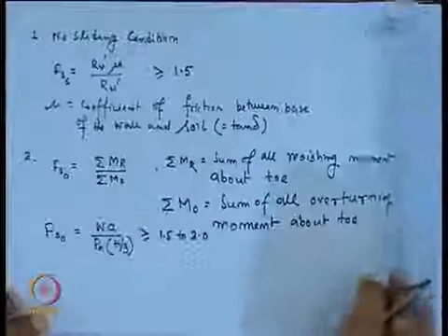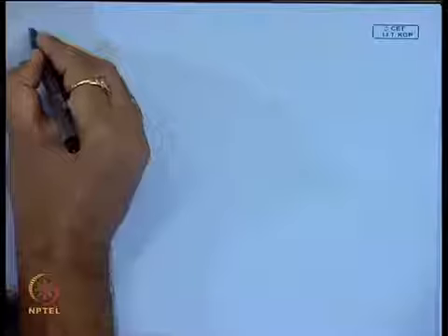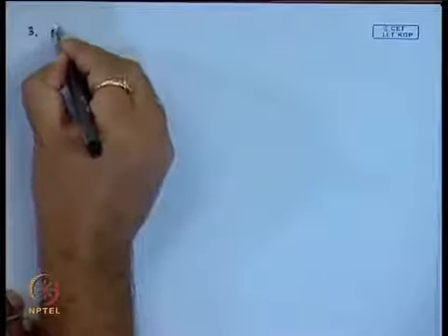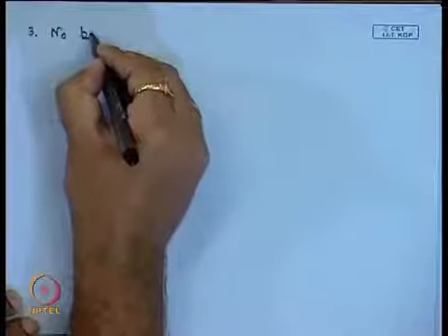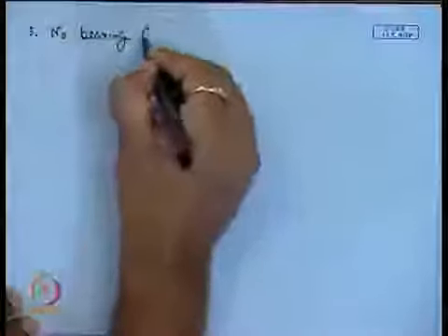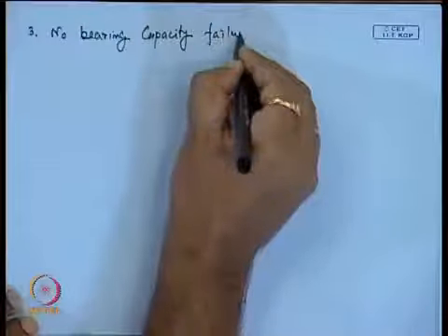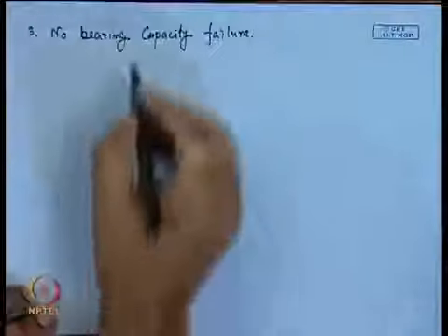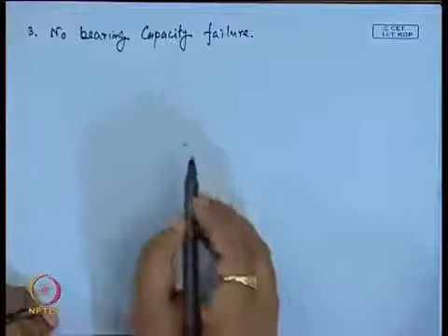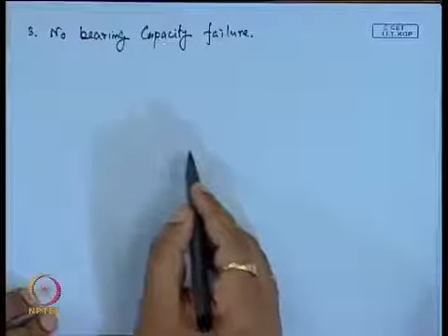So, the next check that we have to do is the bearing capacity check, that is, no bearing capacity failure. If the base soil or foundation soil is very poor, then there is a possibility that the soil will fail because of the vertical load coming on that soil.